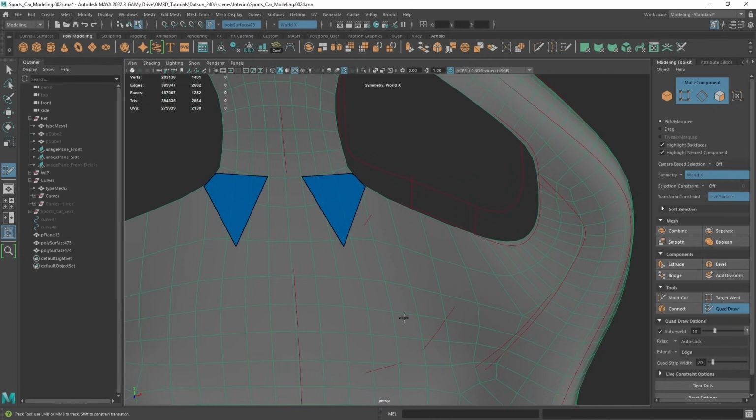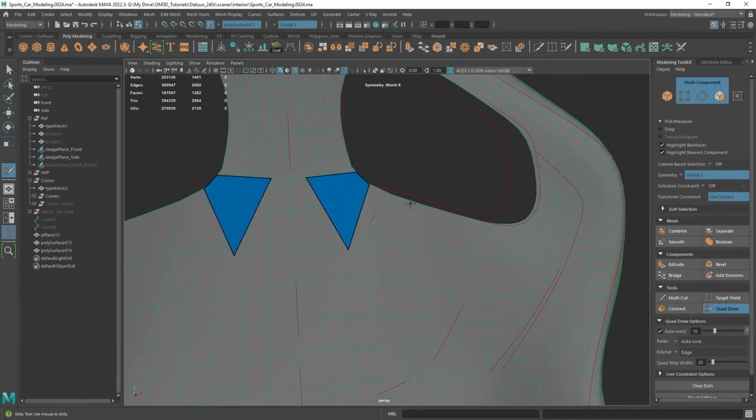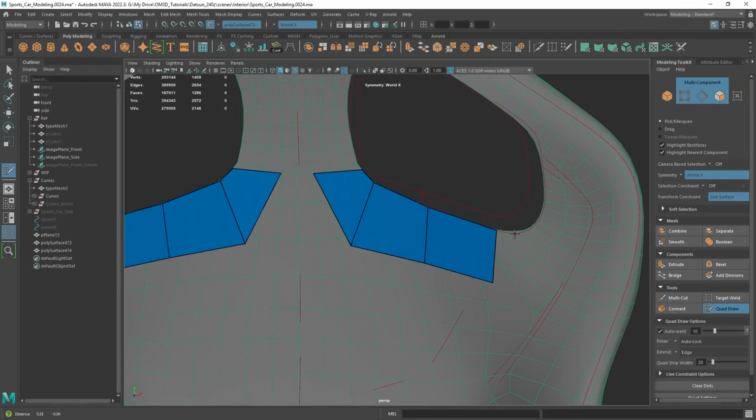If you've never used Quad Draw before, I cover it in quite a few videos, but the way it works is you enable Quad Draw mode with the live surface and then start left clicking points. Once you create 4, as in quad, hold Shift and left click, and there you go, it will draw a quad. Then you can hover anywhere that it sees 4 other vertices and it will create a quad.